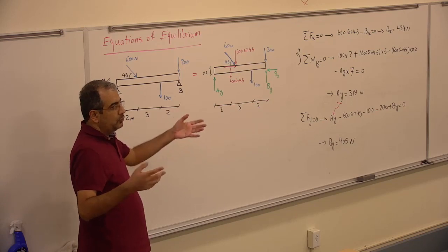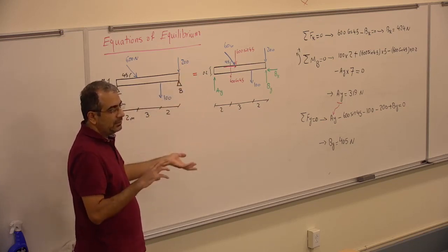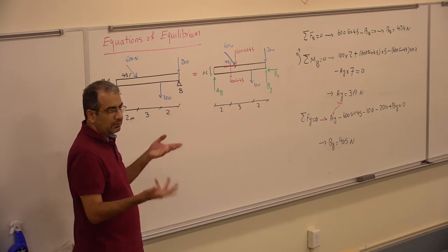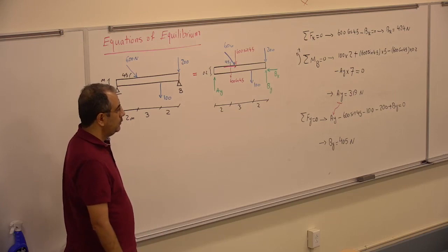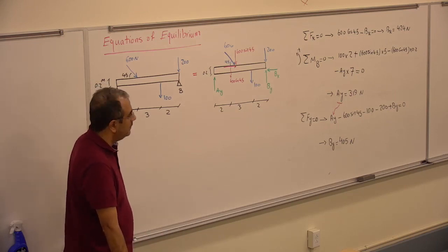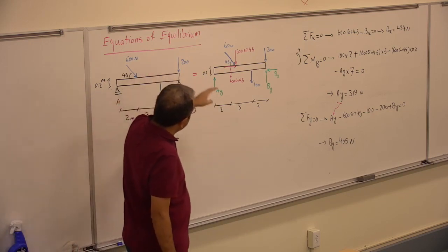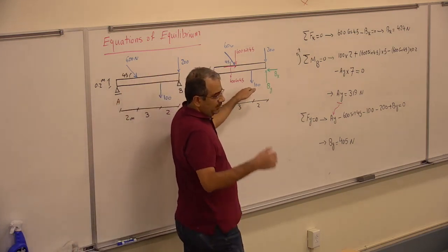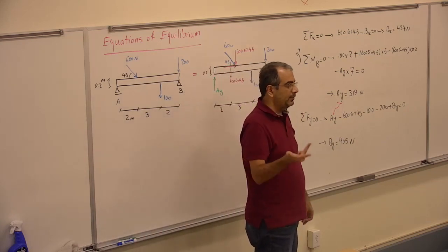Again, you could have used any other order of equations. It just makes it easier or harder. It's not wrong or right. By practice, you learn which equation to use first to make the problem easier to solve. So, the object, then the free body diagram, then sigma fx, sigma fy, sigma M0 in the order that makes it easier to solve.